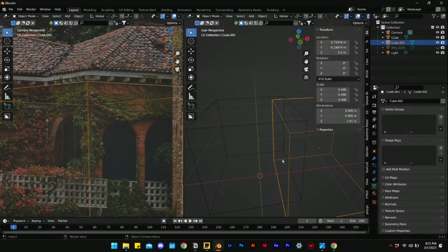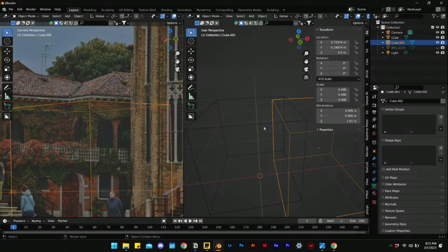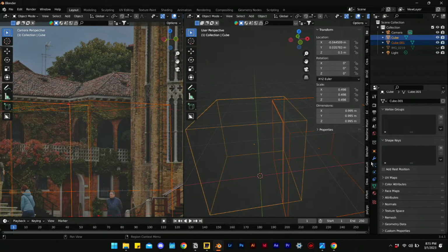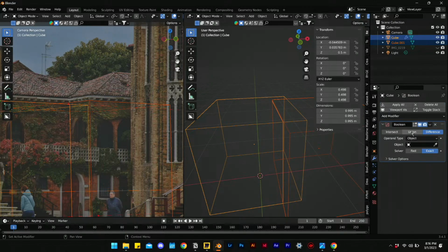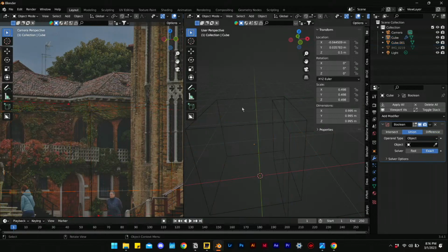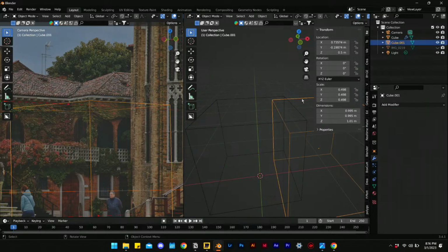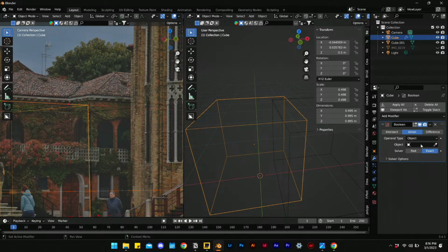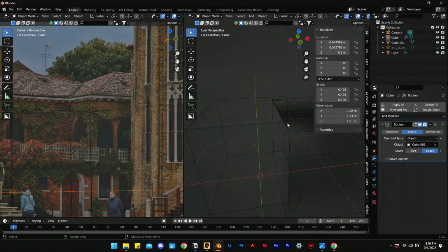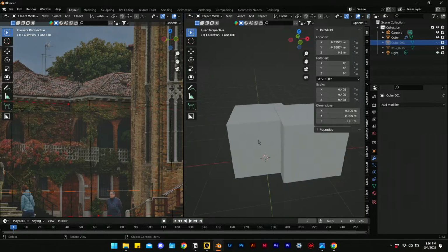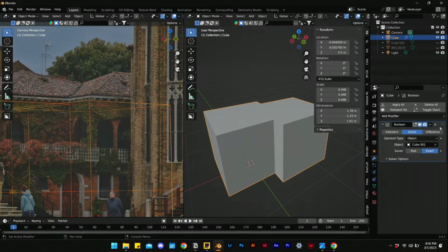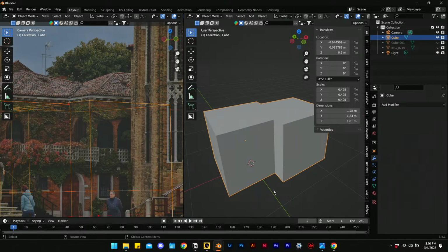With that being said, I can just use these cubes to build out this entire volume. So by selecting these two, I can go over here to modifier, boolean, and do a boolean union, right? Whichever one I apply that to. So I applied it over to this one. And then the object I want to boolean into is this other one here. So I can just hit the eyedropper, select that one there. Now if I hide this second cube, this first cube should look like that two together. So I'd apply this drop down menu for apply, or Control A to apply the modifier.